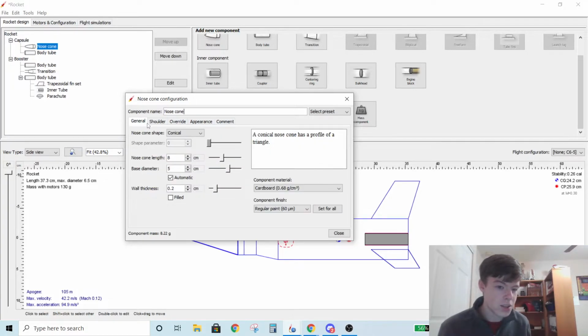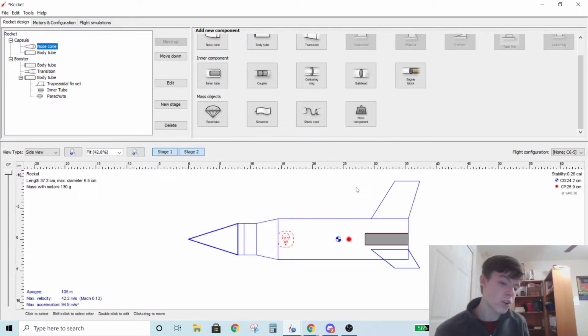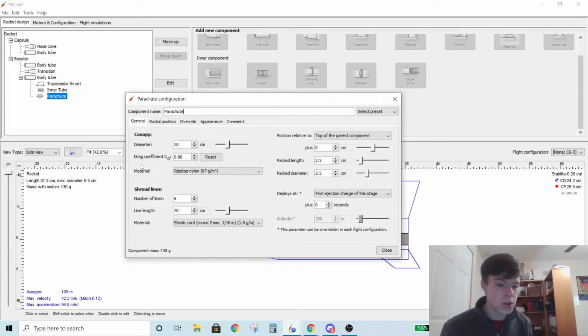And the reason is because OpenRocket simulates all the aerodynamics for you much more accurately than just assigning some coefficient of drag will. So the parachute's the one place, because OpenRocket can't simulate parachutes. You just find this experimentally. But there are roughly accepted values that you can just look up. So that's the main thing for the parachute.